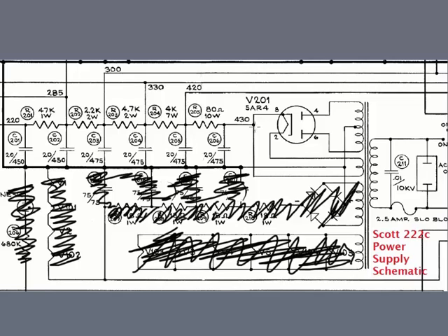So if you've got 430 volts sitting right here, and remember the whole voltage divider thing? Well, guess what? Here's a resistor, and a certain amount of voltage is going to get dropped across this resistor. In this case, I haven't done the math, but 10 volts have been dropped. You know how I know that? Because they're telling me that right here at this node, there's 420 volts of DC voltage.